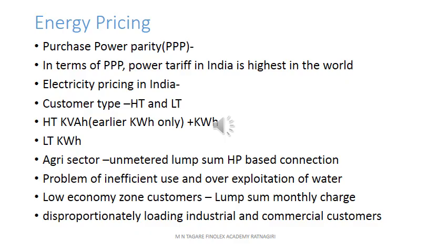Okay, but as far as our topic is concerned, you just have to understand that in ST billing, there are two parts. One is maximum demand and the second one is now apparent energy consumption. So this is what ST pricing is. Now what about LT pricing? LT pricing is a little bit simple. Whatever energy you consume, based on that you will be billed every month.